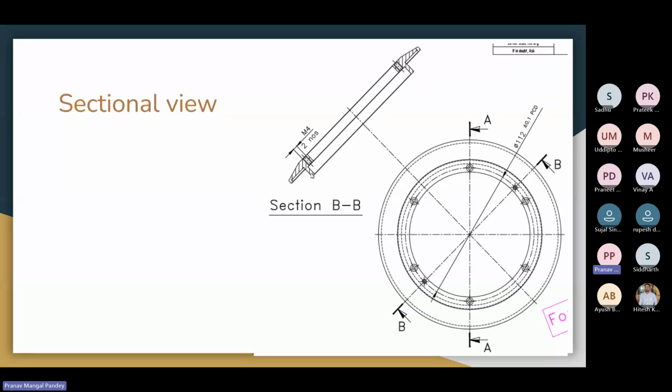The dashed part will be cut out, and the hollow part will be solid lines. They won't be dashed like this. So even in the screw part, you can see there's an axis, a dashed line, but there are no dashes to fill the whole part. So sectional views are sometimes used instead of any of the front, left or top views. You have to make sure sometimes you use this.